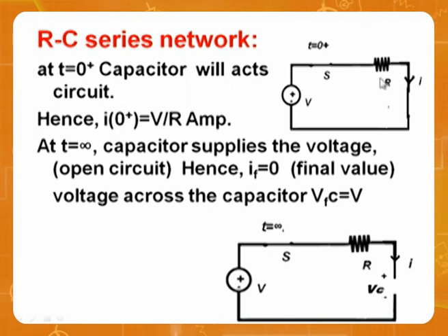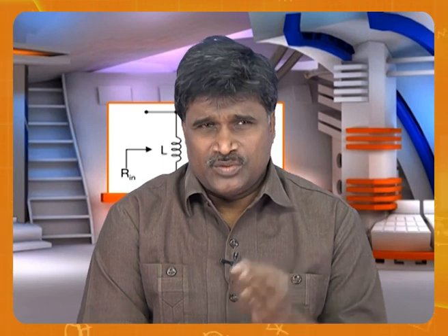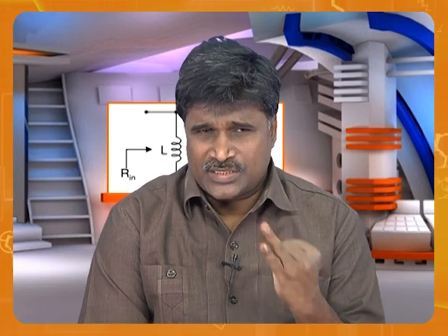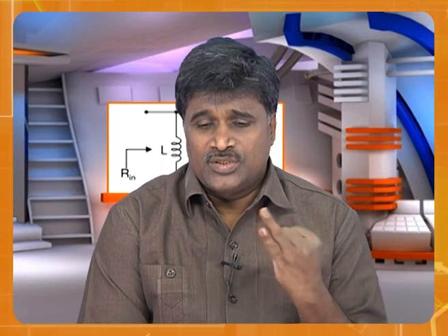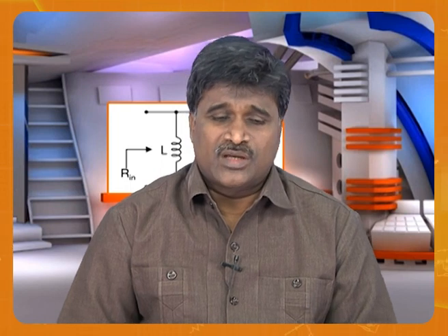Similarly, when you talk about RC circuit, how is this? This is not connected. Not connected means 0 voltage. If you keep it for a long time, total voltage comes. So initial and final values you can also get from physical circuit. Therefore, I am giving you 3 approaches to calculate initial value, final values: using the time domain approach, using the S domain approach, and finally using inspection or physical diagrams you can always get.